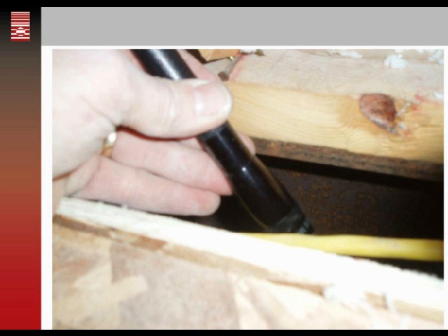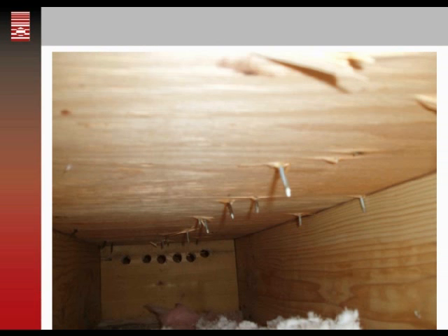Additional bypasses. This is looking down the 2x10, 2x12 joist space. Some locations they had blocking with holes drilled in. If those holes were open to the soffit, we'd feel below zero air coming up through there, and we certainly didn't. There wasn't much movement, if any, coming from the low soffit venting.